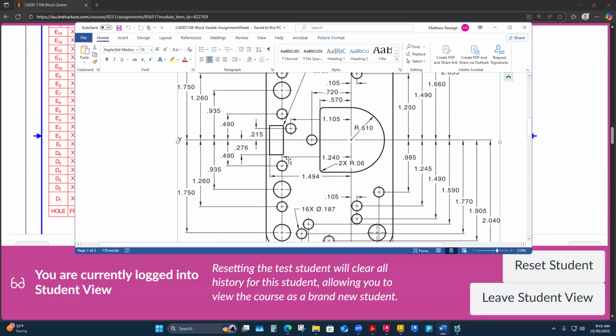I think this is how I interpreted what had happened. I think the 1.24 was supposed to have the arrow go to the rectangle, because they show they're lower than the 1.24. If I would extend this center line, I felt like all of these were on the same center line. But I think it's arguable because I'm missing a clear dimension.